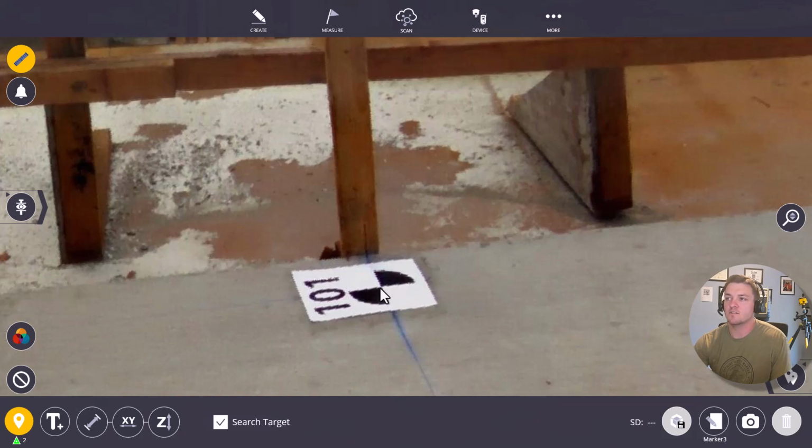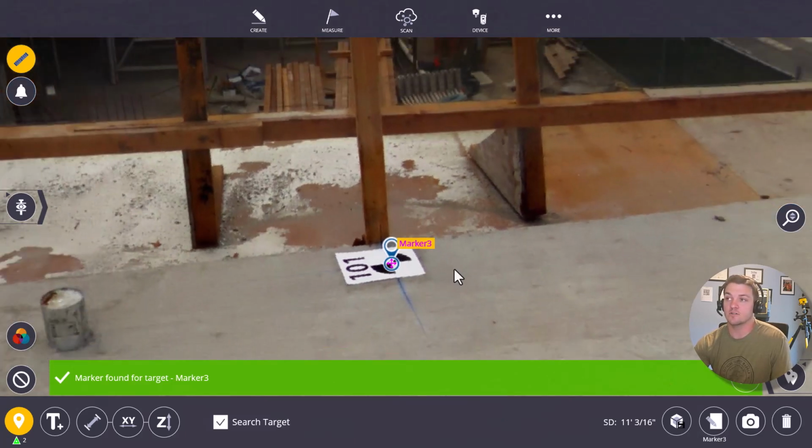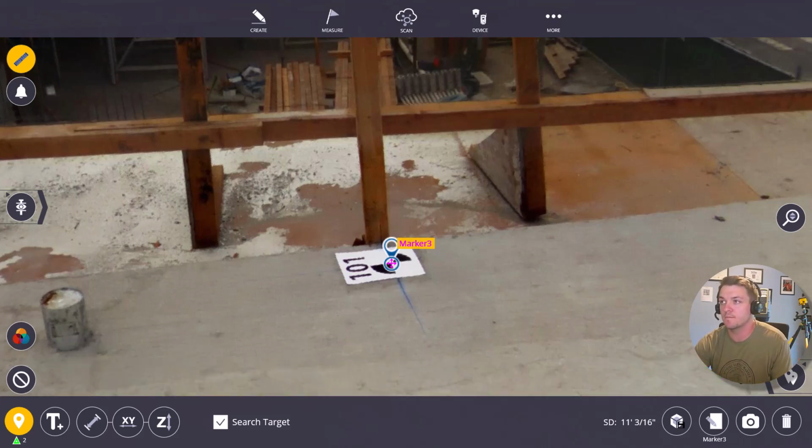So if I go to the station view and then go to the measurement tab up here and then go to search targets and click on it, it'll find pretty much any normal target there. Now, these markers, when I export a TDX, will come into RealWorks for a traditional georeferencing, which is going to, if I have them spread throughout the site, do a better fit over the entire site. I would suggest probably a resection for smaller areas, but as you go a couple hundred feet away, again, any azimuth error is going to grow there.